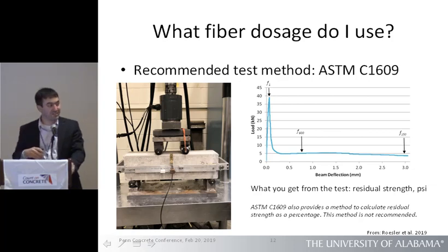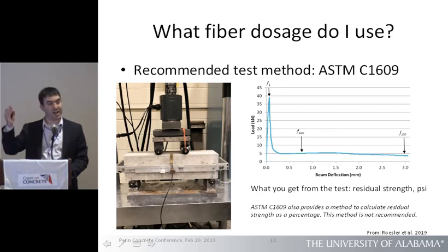But if my capacity, my tensile flexural strength of my beam is 800 psi, well, that same 20% is now a much higher number. So the percent does not give you a good indication of the actual capacity of the beam, because if you just specify a certain percentage target, you could have a really low MOR or just an acceptable MOR and then inadequate load carrying capacity.